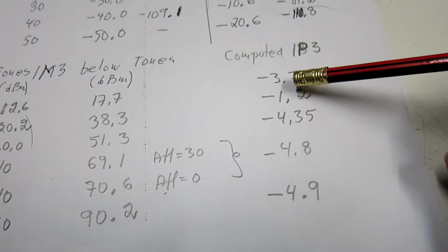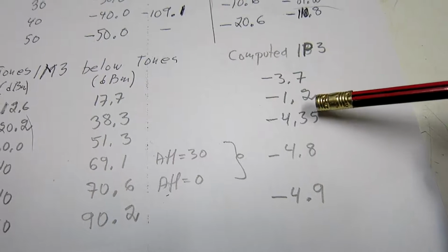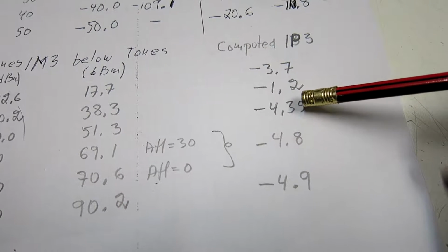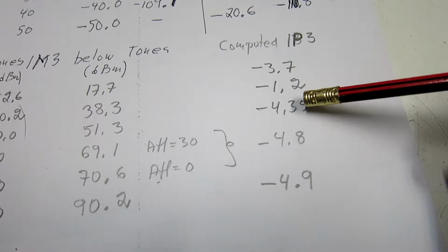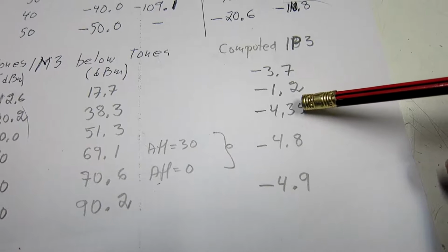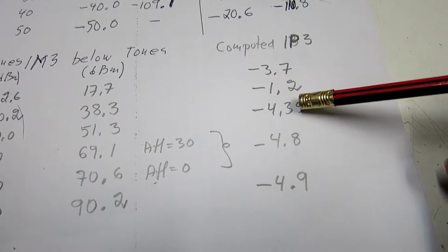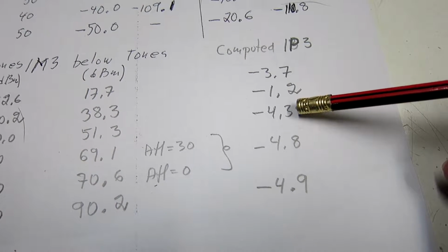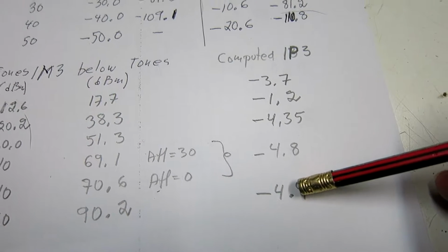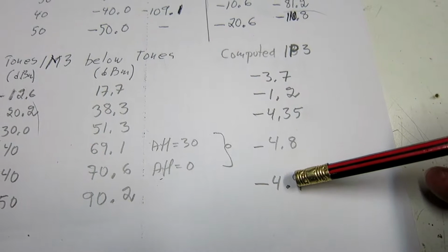But as the level goes down, I think the IM3 from one of the possible sources is going to dominate, and we would get an IP3 value that is the same regardless of the signal level. And that's the normal rule.